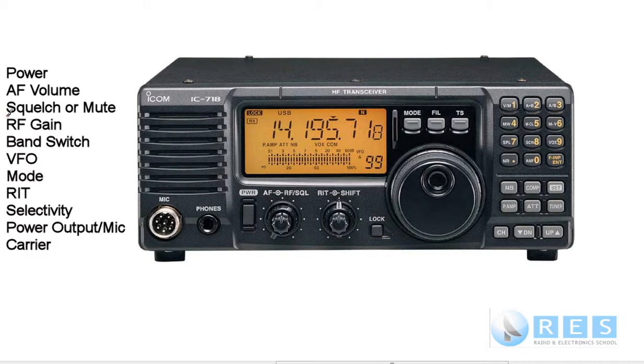The next one is the squelch or mute. It's called a mute on FM, and it's called a squelch on AM and single sideband SSB. And the purpose of the mute is to remove any noise from the receiver when there's no signal being received.